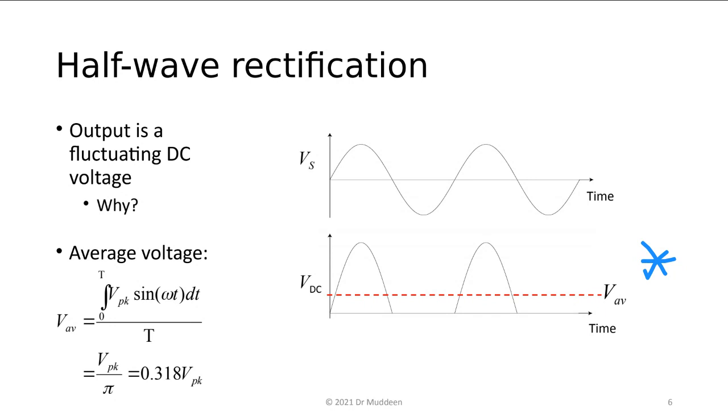So because it's rectified, you have a signal that starts, goes positive, comes back to zero, goes positive, comes back to zero. So it's always positive, going from zero to some maximum. That's a DC. It's not reversing polarity, and of course, it's fluctuating all over the place. There is an average value though.